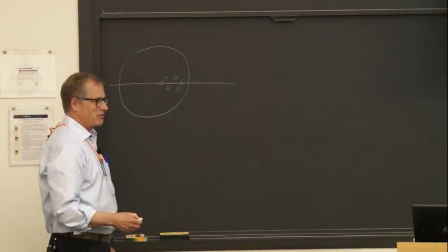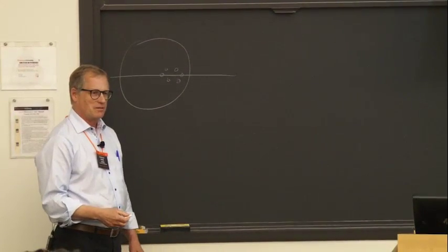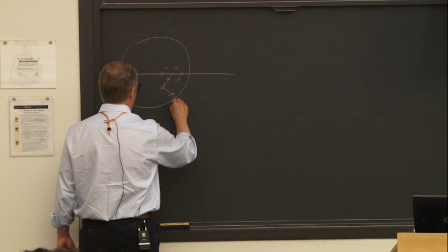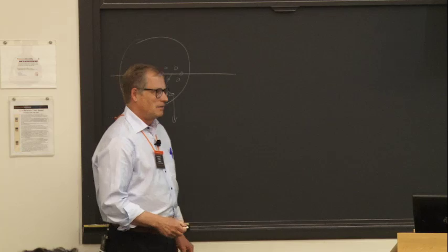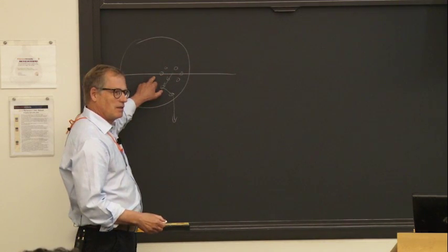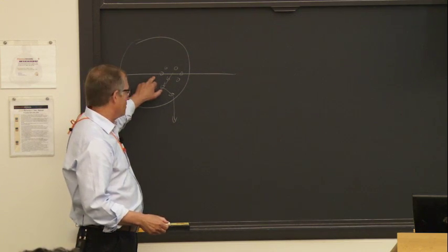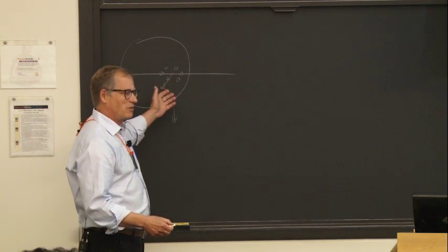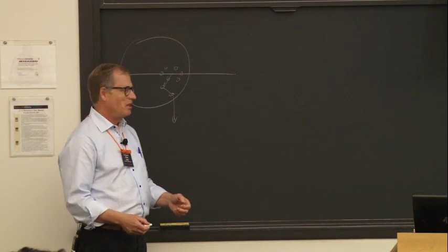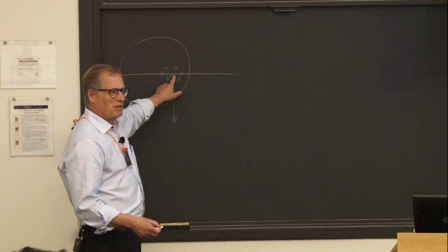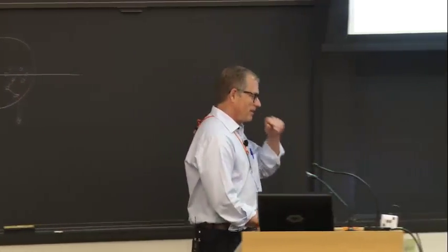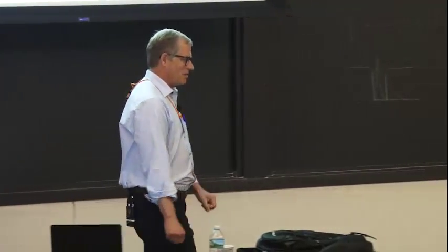And you saw what Mie scattering does. It sends light in various directions. So light's coming this way, then it hits a drop, then it goes that way, and then it comes out this way. So if you're trying to correlate the behavior of something inside here, this makes no sense, because it's totally displaced. Remember I was talking about needing 15 particle pairs inside an interrogation cell. Well, which interrogation cell does this belong to? When something's optically thick, you're losing the signal as it comes out.